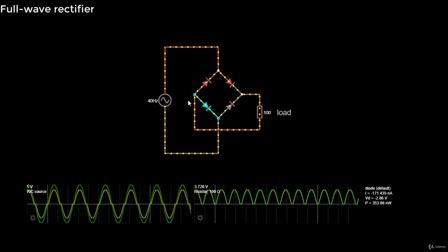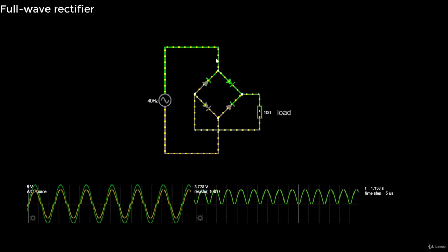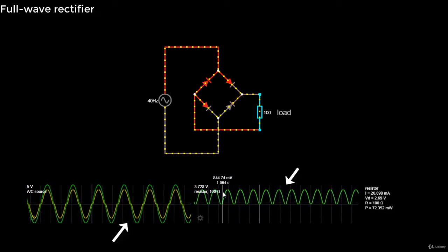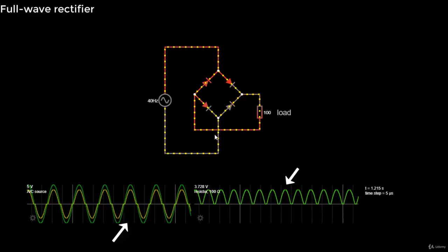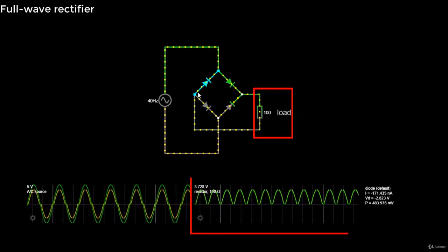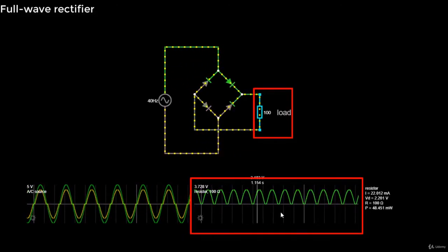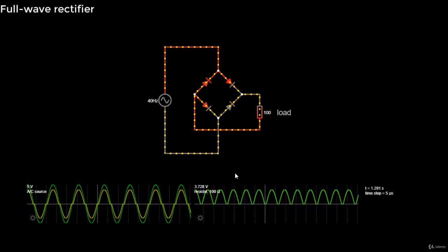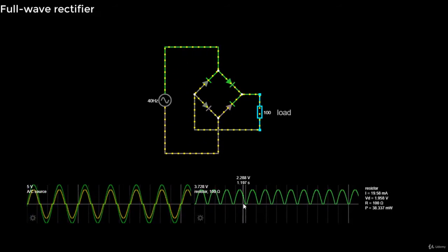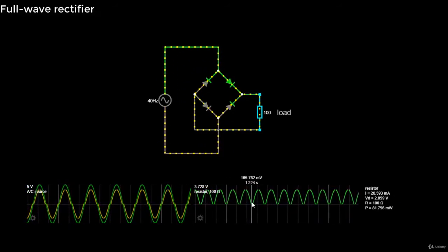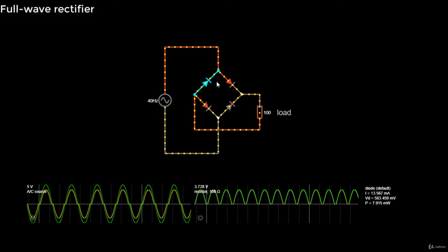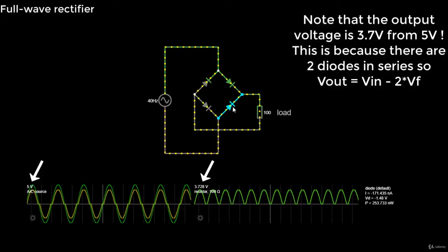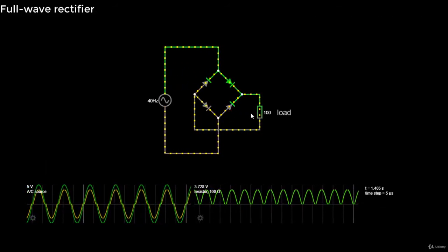The next circuit is a full-wave bridge rectifier, which uses 4 diodes to convert those negative signals into positive signals. The signal across the load can be seen here, and note that the entire input waveform is used. The gaps at 0 voltage occur because of the diode's forward voltage drop. In this circuit, 2 diodes are always in series with the input. When you design low voltage power supplies, for which the diode drop becomes significant, you have to remember that.